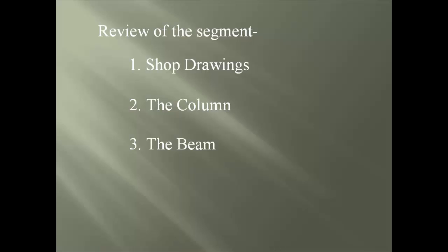Then the third item was the beam also found in these shop drawings, and just like the column, you saw the specific dimensions that will align the beam in place for not only the erection purposes, but also the bolting and welding purposes. And lastly, we introduced you to the metal deck shop drawings, and you again see how they are very similar in style to the design drawings, plus having the individual sheet or bundle information stated along with the orientation within a specific section.